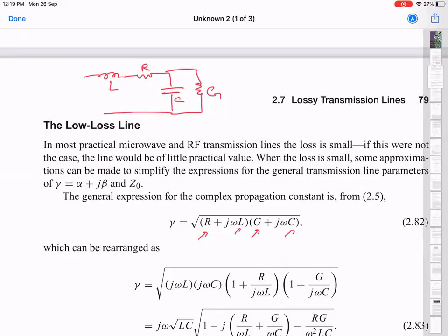And that creates a problem in a cryogenic environment, because in order to keep the cryogenic environment cold, you cannot have a thermal load also coming. Just the very fact that there's a piece of wire going from 300 Kelvin down to say 10 millikelvin or 300 millikelvin, or whatever your experimental temperature might be, you can dump thermal load. So there are special cases where the losses are actually there and one needs that, but in most cases we will not worry about it.